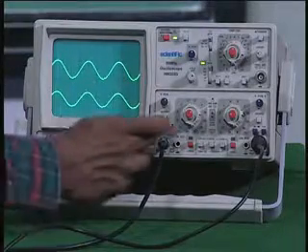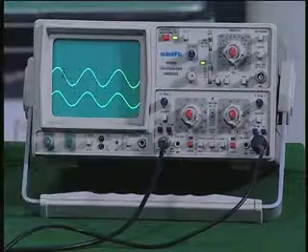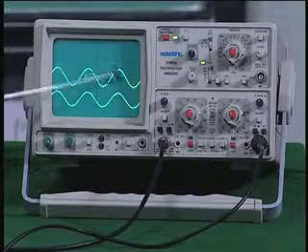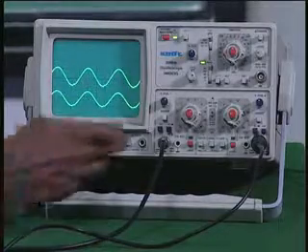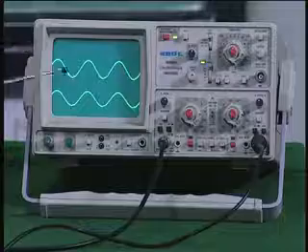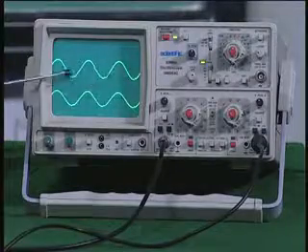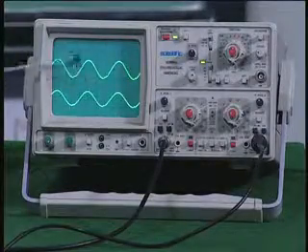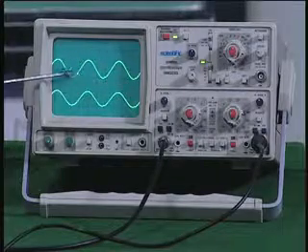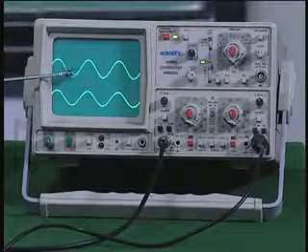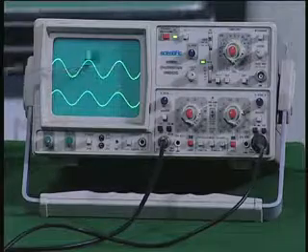So that is what actually, now you see it is symmetric to the central line, and when I DC couple it, you find it moves up to this. That means the entire output has moved with reference to this as the reference line or the 0 line. So I have clamped it positive.